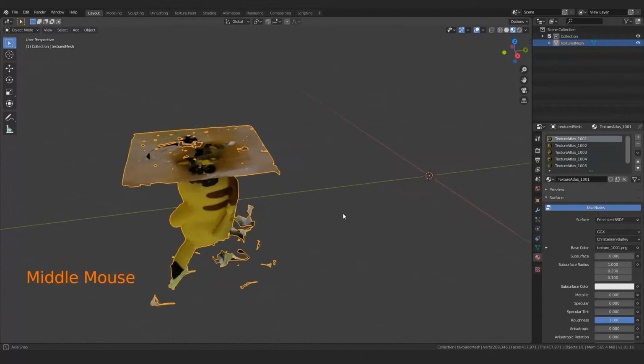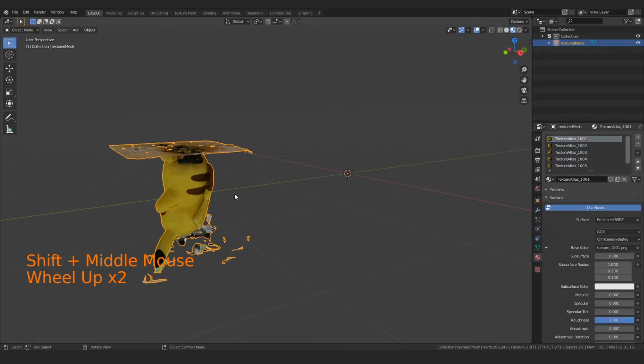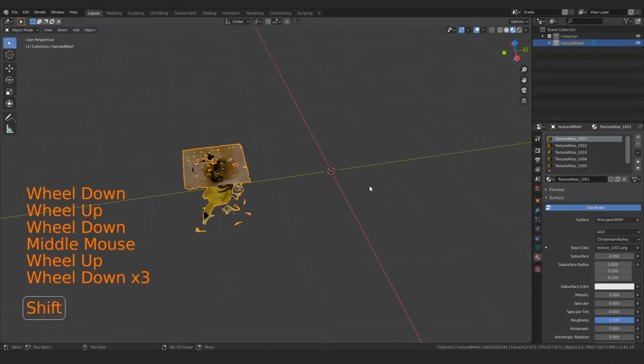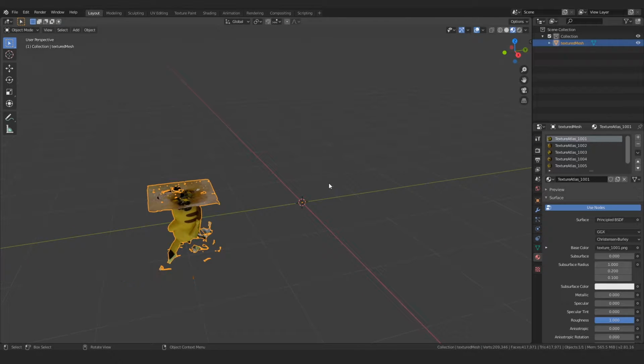All right, so what we need to do now that we've kind of gotten all that out of the way, is we need to center our mesh in the world. So let me talk a little bit about the 3D world space, since this is the beginner video, and explain to you exactly what's going on here. So we have this mesh that's been imported, and Meshroom has itself kind of determined where it wants to put the mesh in the 3D world, and Meshroom tried to do its best, essentially. It tried to orient this object in the world, but you can see that it came in upside down and kind of rotated around and offset from the center. We're going to fix that.